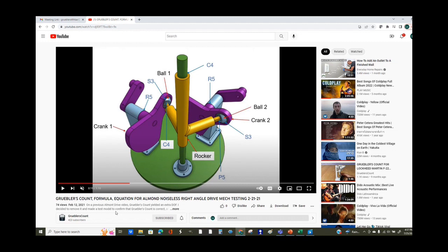So do you see this mechanism here? Yes. Okay, so what I did here, this is before 3D printing. I machined all this. This is a landing gear for a jet fighter, an A4, and to let it dampen for this model, I put an air cylinder here. You look at the air cylinder, it has a spherical joint at the end here. Since it's spherical, this rod actually rotates, right? But then down here, to keep the body from moving, I put a universal joint. And that is anti-click clack. That prevents it from rotating.